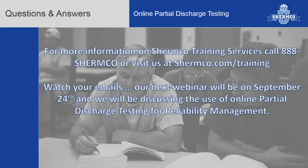Now, the equipment that Shermco typically uses is not the permanently attached long-term monitoring type equipment. Most times our technician goes out to a particular client maybe on a quarterly basis and runs a survey on their equipment. However, in answer to your question, yes, some of the equipment out there on the marketplace that is designed for permanent installation and continuous monitoring can be very sophisticated. You could actually put in thresholds for warning and alarm, and when the PD activity is sensed at these levels, some of them are so sophisticated they'll actually send the person in charge, if it's the reliability manager, whoever it is, an email or a text message saying a warning level has been detected. And a lot of times it'll even report back which sensor is reporting that condition. So yes, it can be very, very sophisticated.